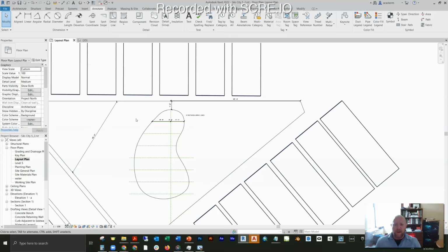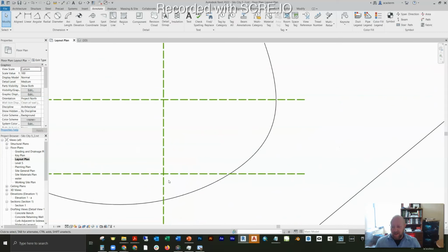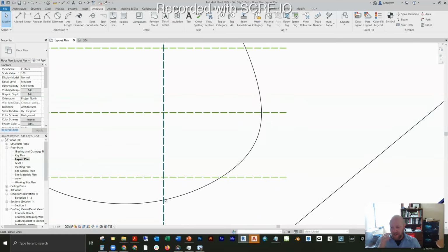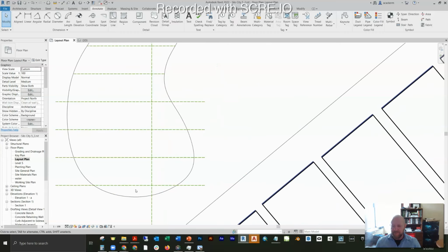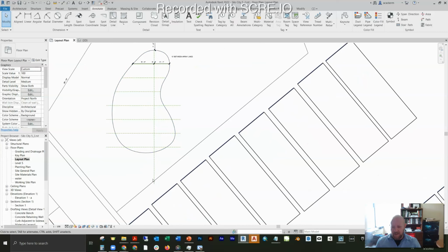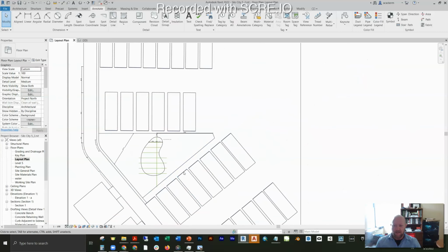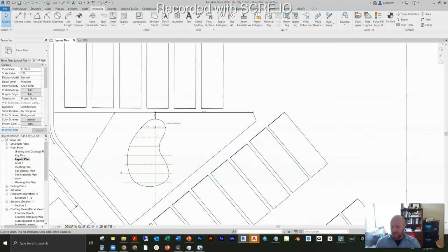And then, of course, with our array, we have equal spacing. Down here, we've got something a little less regular. So we would draw a little detail line here, right? And we might also draw one from the center of this line up. And we dimension it down to here, and we'd also pull a dimension off here. So that's how we'll deal with this kind of geometry.